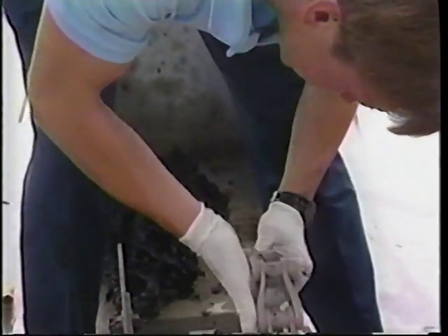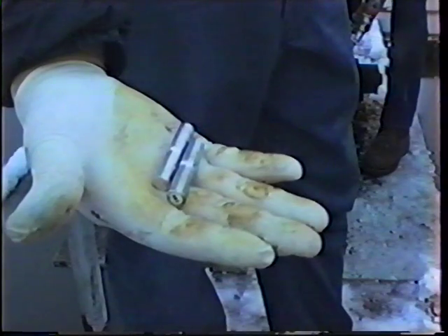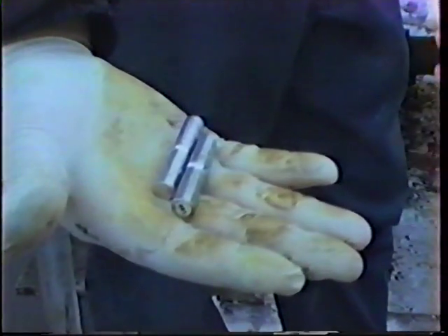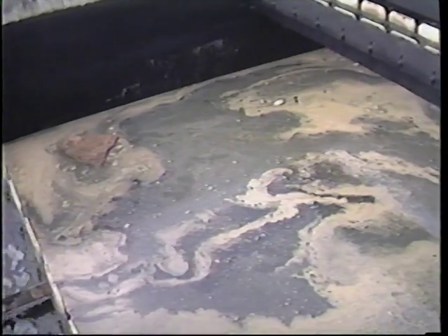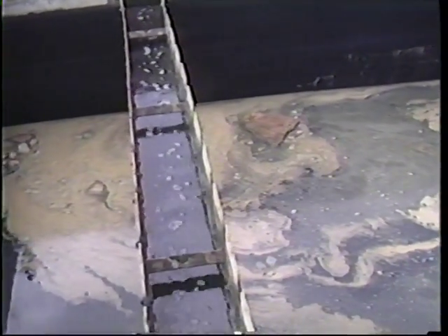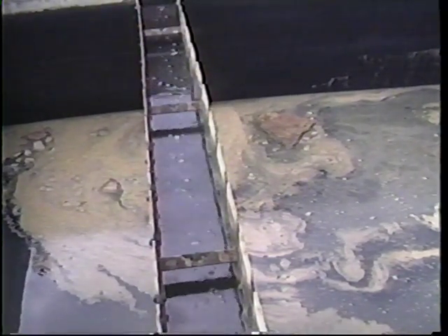If the motor and gearbox are turning and the drive sprocket is not, the problem most likely is a broken shear pin. Shear pins tend to break more frequently in winter months when ice on the clarifier surface interferes with proper operation. An excess of solids in the clarifier, the presence of debris, or a mechanism jam can cause a shear pin to break as well. In any event, the cause of the shear pin failure should be determined before restarting the mechanism.